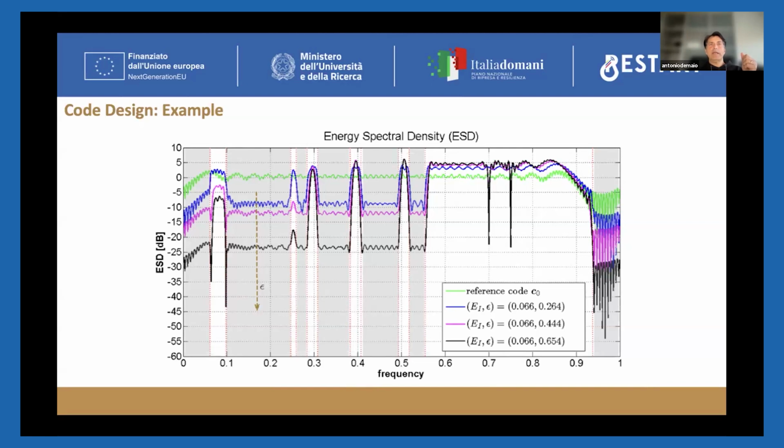We can also observe that by increasing the parameter epsilon, according to the arrow here, we are augmenting the degrees of freedom that we have in our optimization problem. Smarter and smarter distributions of the usable energy in the spectral domain are achieved. There is also a progressive reduction of the radar emission in correspondence of the shared frequencies, as well as an enhancement in the rejection of the unlicensed jammers. As a result, we expect higher and higher SINR values.